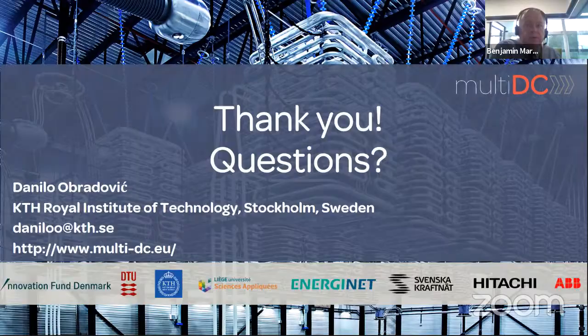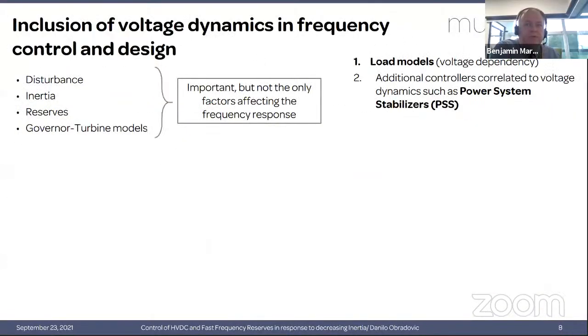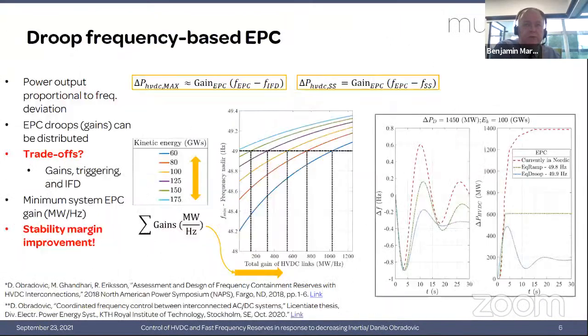So the practical requirements for response are very different. And so as TSOs go around their systems, they do need to be conscious of the levels of response they're offering out between isolated islanded areas, because those areas have less degrees of freedom to accept those sudden demand changes that the response will represent to their systems. But it can be managed and optimized.